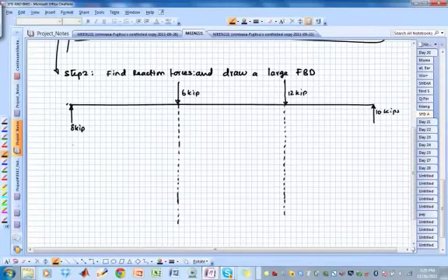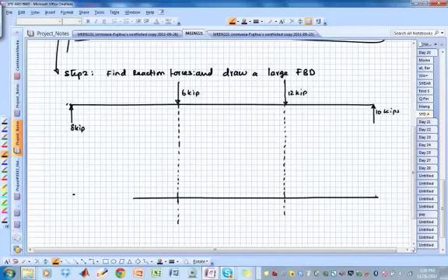Okay, so I'm going to draw another line right below it so that we can draw the shear force diagram. Leave yourself plenty of space because the shear force diagram goes both positive and negative, so make sure you have space and draw it with the same length right underneath, like what I'm doing. Okay, so make sure you are drawing it right underneath.